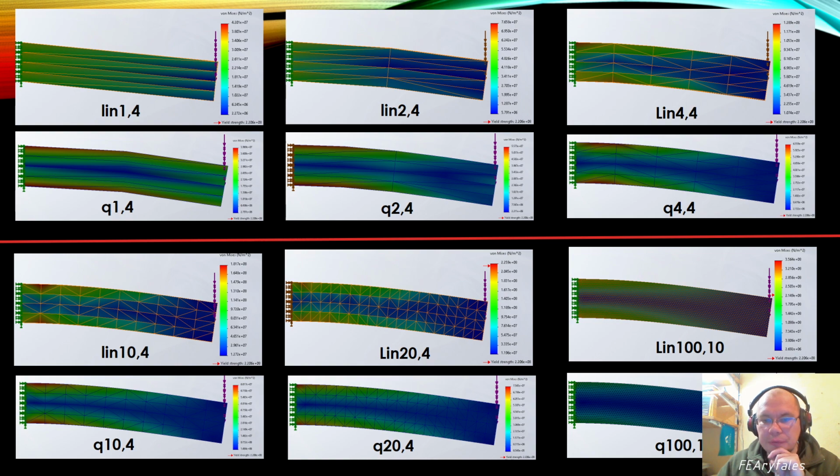Here you can see a different example with different mesh. Here you can see two types of picture. The top one is linear, the bottom one is quadratic. Here, 1 element per length, 4 elements per thickness, because someone told you that you need to have 2 or better 4 elements per thickness, so it's not only elements per thickness we need.